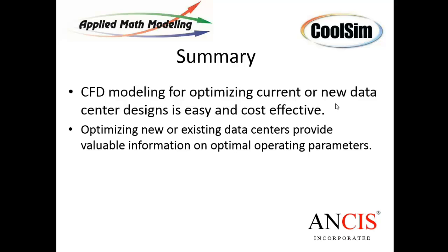I think what I do many times when I do CFD simulations for other companies is we're looking at the extreme cases. If extreme cases pass, it means that all other cases in between the extreme cases will pass too. Yes. So you can bracket your problem. Right. You bracket your problem.